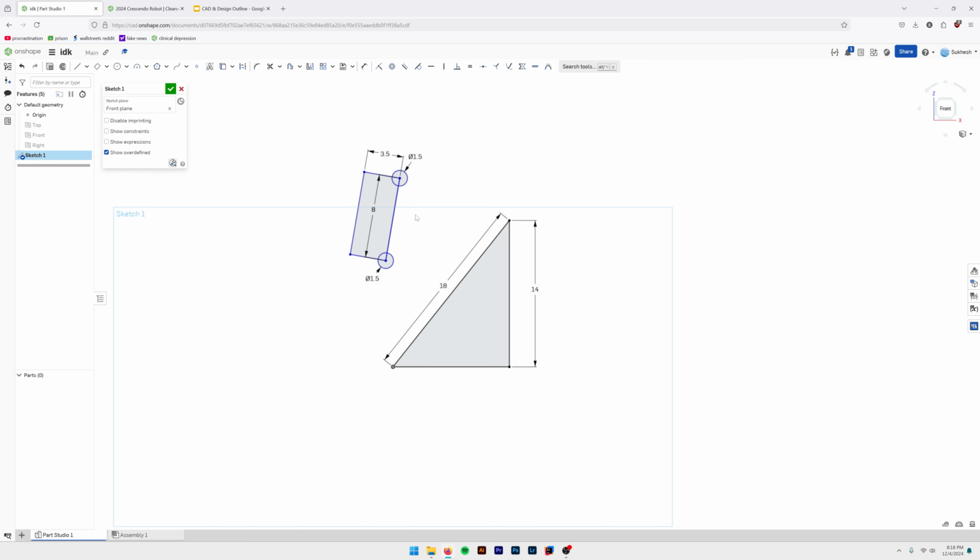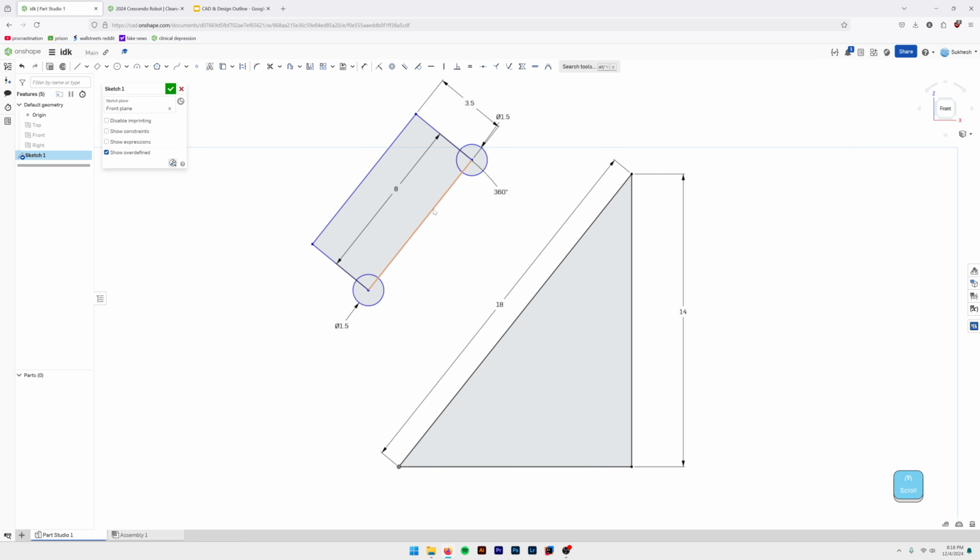So how would we do that? There's two ways I could think of doing this. I guess you could try dimensioning this with the slope and then setting that to 0 degrees, right? So now we have the line that is 0 degrees with this line, meaning that it's parallel.